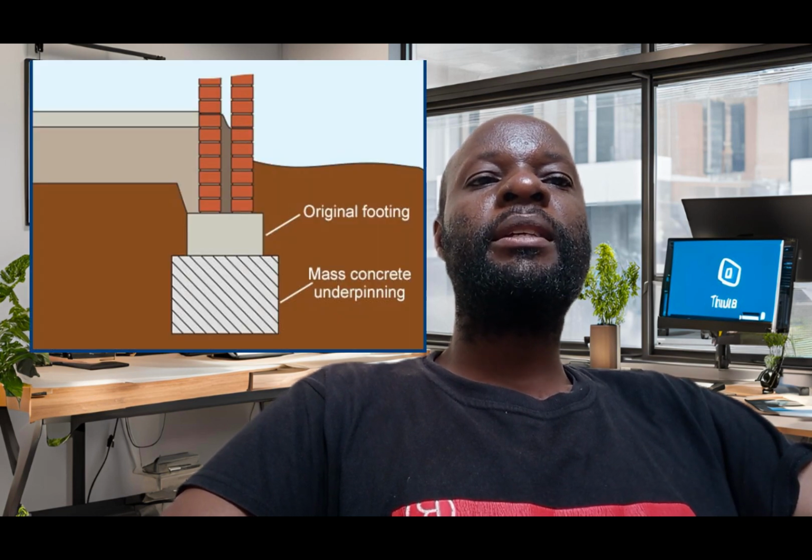So this underpinning method is used where a lot of digging is not required. A concrete foundation is poured to increase the strength of this base. So this is a very easy underpinning method, and it doesn't require heavy machinery. Also, it is a very cost-effective method. And from the pictures beside us, you can see what we mean by mass pouring underpinning method.